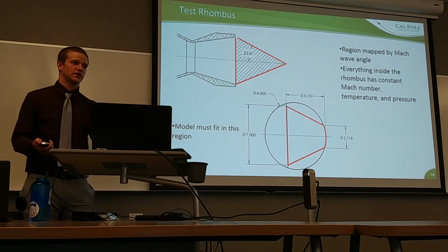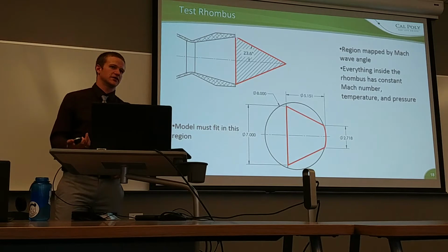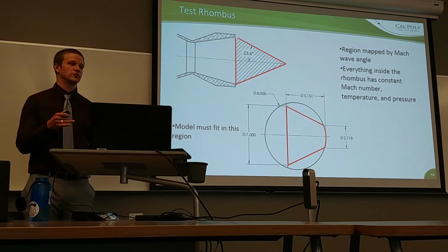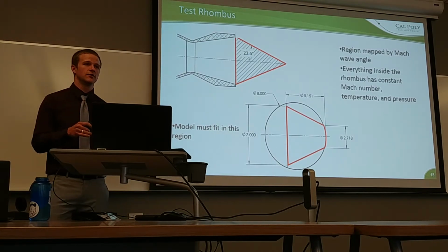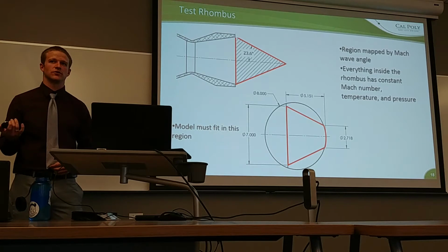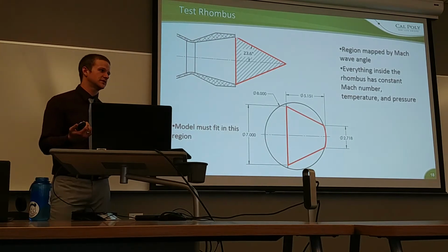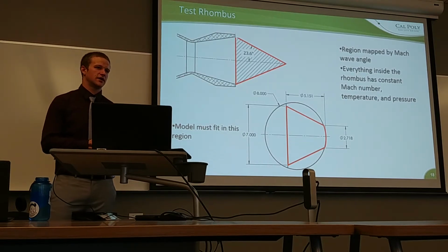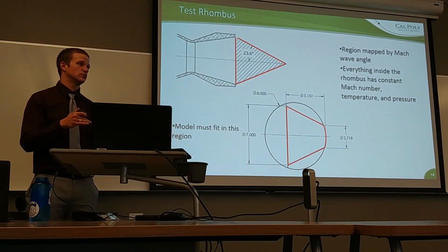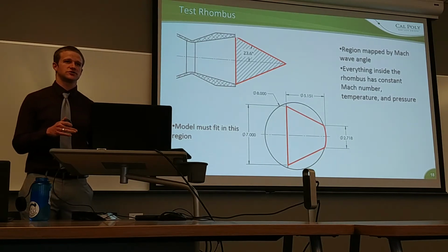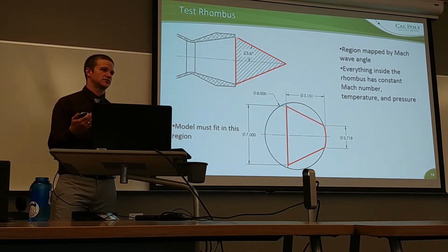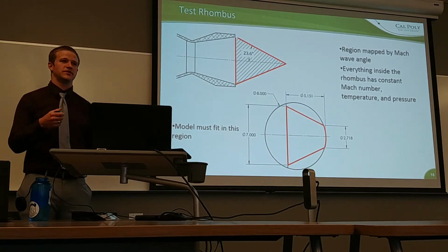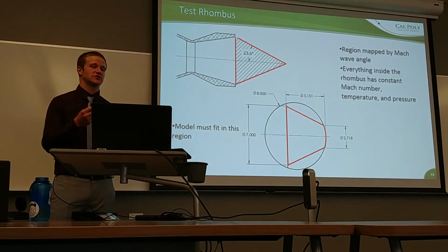So we did not observe any condensation, and Dr. Doig was asking if I was able to calculate exactly when that would occur. The temperature and pressure that we reached is well below the condensation point for air. But the literature, using Pope and Goin's book on supersonic testing, discusses that you can subcool a flow, bringing it below the temperature at which condensation would occur, but if it happens quickly, condensation doesn't always show up, because what's required is not just that the water becomes a liquid, but that the water particles find each other and condense into droplets.